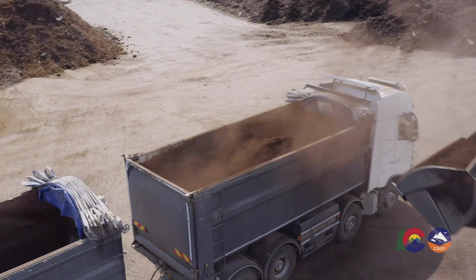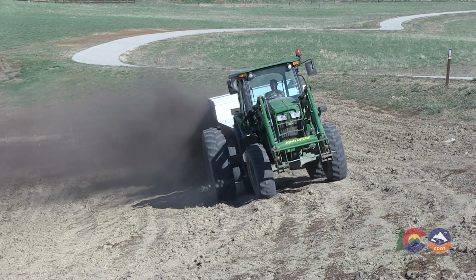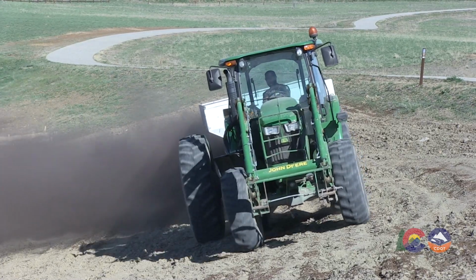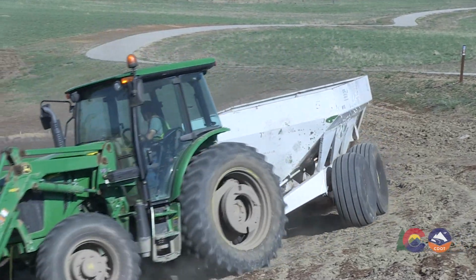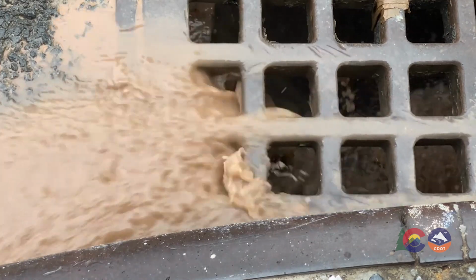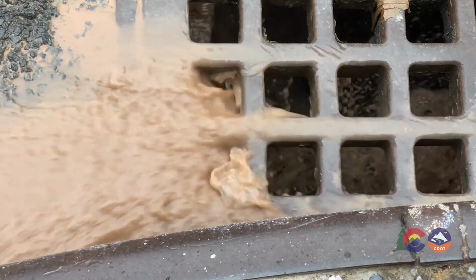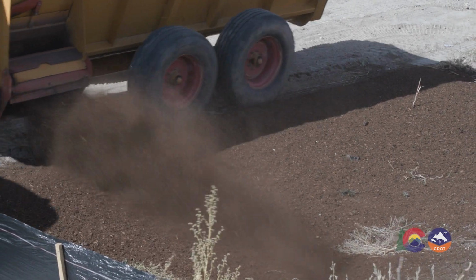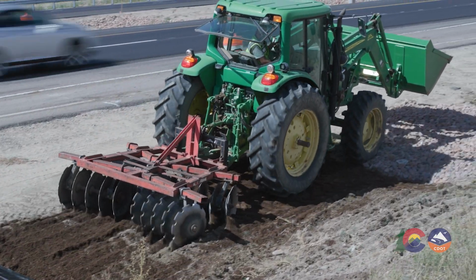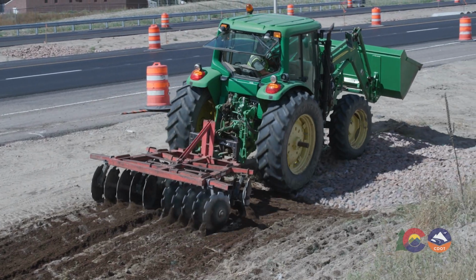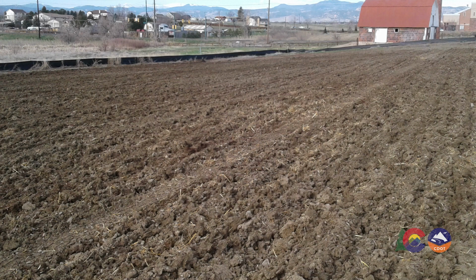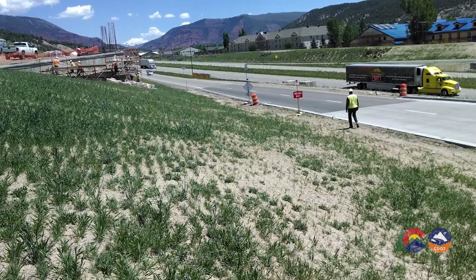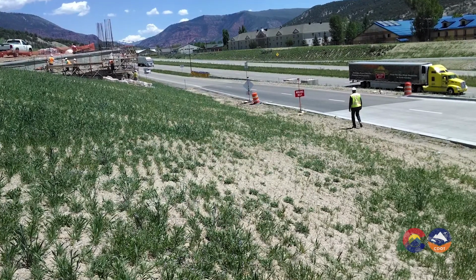Why do we amend topsoil? Topsoil amendments provide nutrients and organic matter that improves the fertility and structure of the topsoil after road construction activities. Topsoil amendments can also help to decrease soil erosion while promoting soil stability. Applying organic fertilizer and amendments enhances microbial activity and increases organic matter, pore space, and nutrient availability. This improves water infiltration and plant establishment, which reduces soil erosion to maintain water quality and improves dust control to protect air quality.